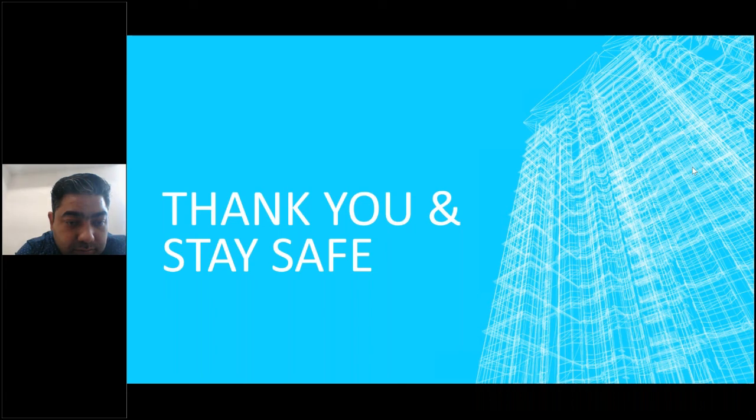And then if you look, there are different standards like BREEAM, LEED from USGBC, and ASHRAE. Then you have the Association of National Home Builders. So there are different entities across the world which have actually put down a standard. But normally what we look forward to is the ASHRAE standard for benchmarking, where we can identify the kilowatt hour per meter square per unit of energy for the annual operation of the building. And this is specifically for a hospital, let's say.